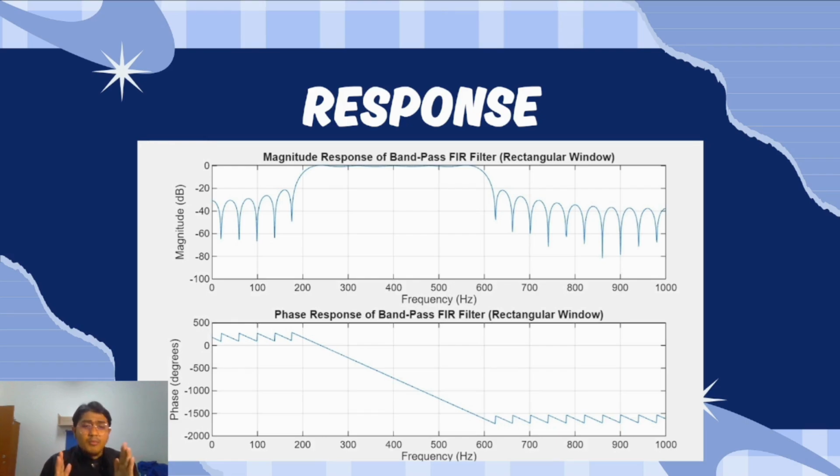However, in both stop bands, we again see strong oscillation, whether at very low or very high frequencies. Neither is fully suppressed. The fluctuation peaks around negative 13 dB, meaning out-of-band signal close to 200 or 600 Hz can still leak through significantly.